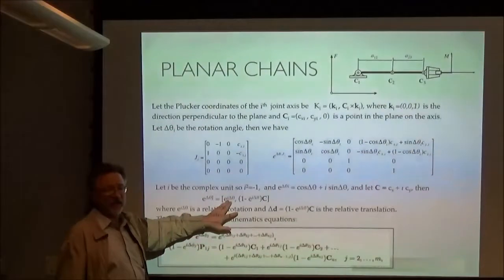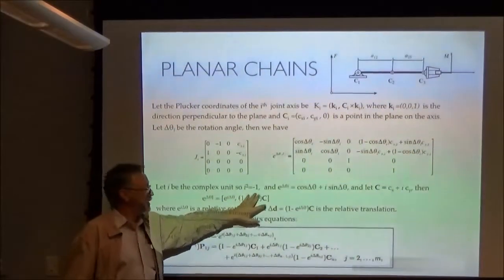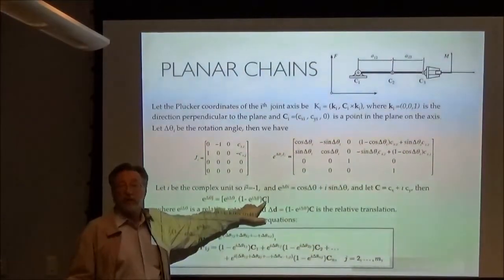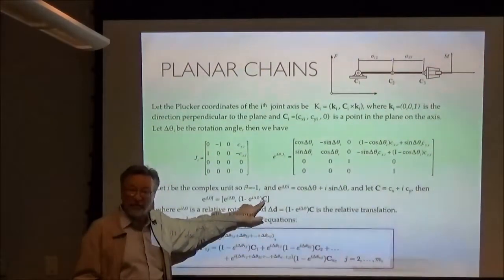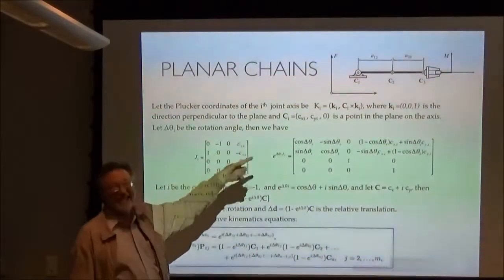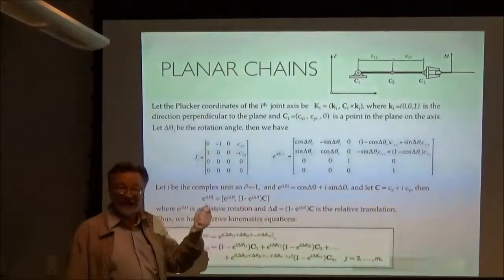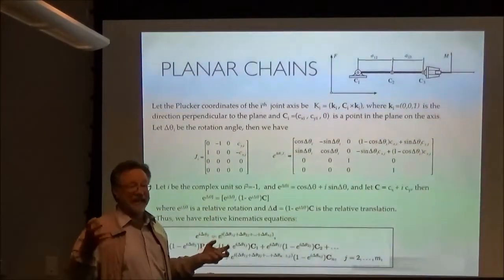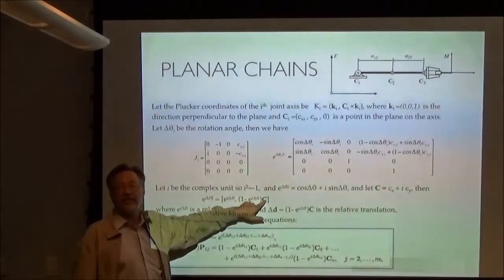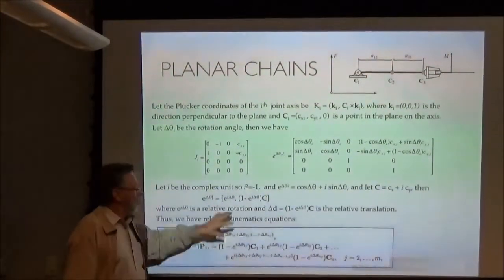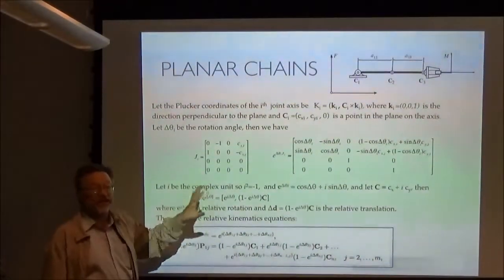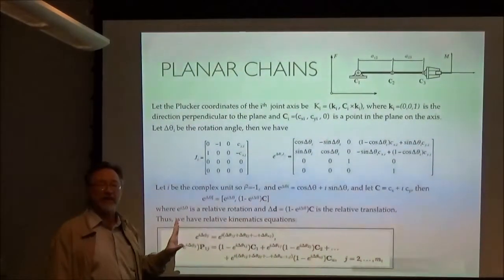This is the standard rotation. This is the translation term written in terms of the pole. You wind up seeing the pole show up in this context because the pole is really there. The pole is your bearing. Okay, so it's got physical meaning. The actual translation vector doesn't quite have the same meaning as the pole of the displacement. Once you have this, you can now write your kinematics equations, which are exactly the robotics kinematics equations.